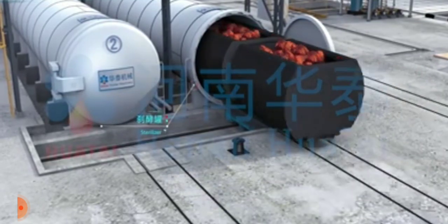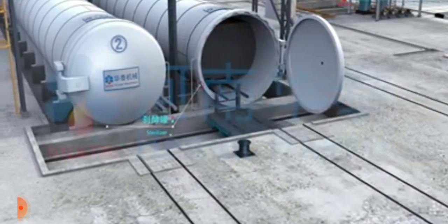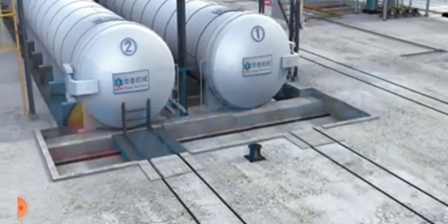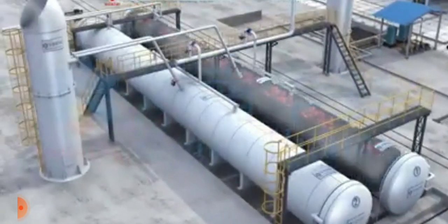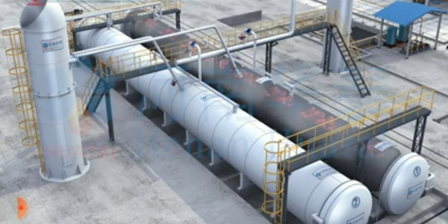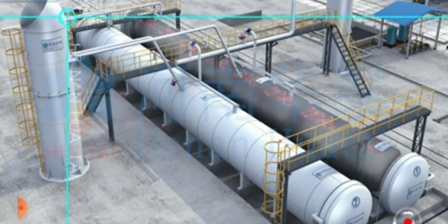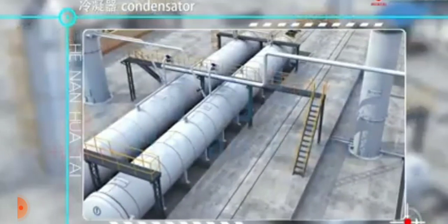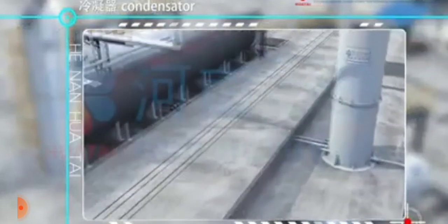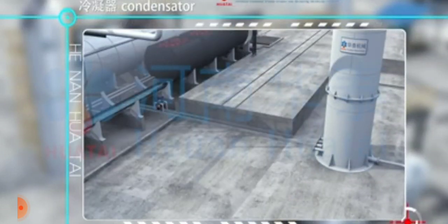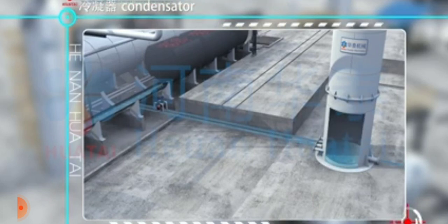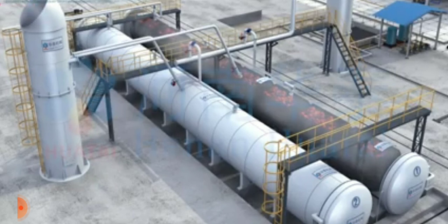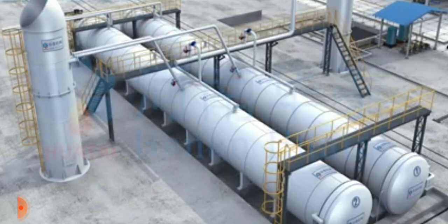For the horizontal sterilizer, after the sterilizer cage enters the sterilizer entirely, close the gate. Start filling with steam. Sterilize palm fruits under certain temperature and pressure. Condensate generated during sterilization is discharged to the condenser from bottom pipelines and then discharged to the sludge oil pit. After reaching the preset sterilization time, empty the steam.